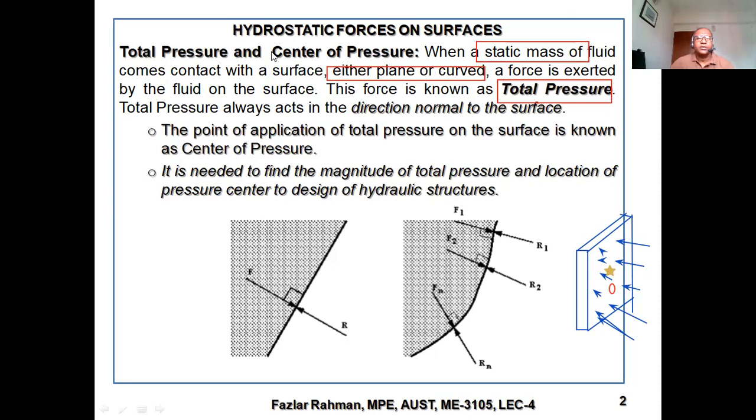Say you are taking a shower from a bucket of water, and you fill up the bucket with water. How does the pressure force work at the bottom of the bucket and other places? Pressure always works perpendicular to the surface. So if you have an inclined surface, your pressure works like that. Gradually it will decrease as you move from the bottom to the top. As you come down, the pressure increases. And at the bottom of the bucket, the pressure will be uniform, right?